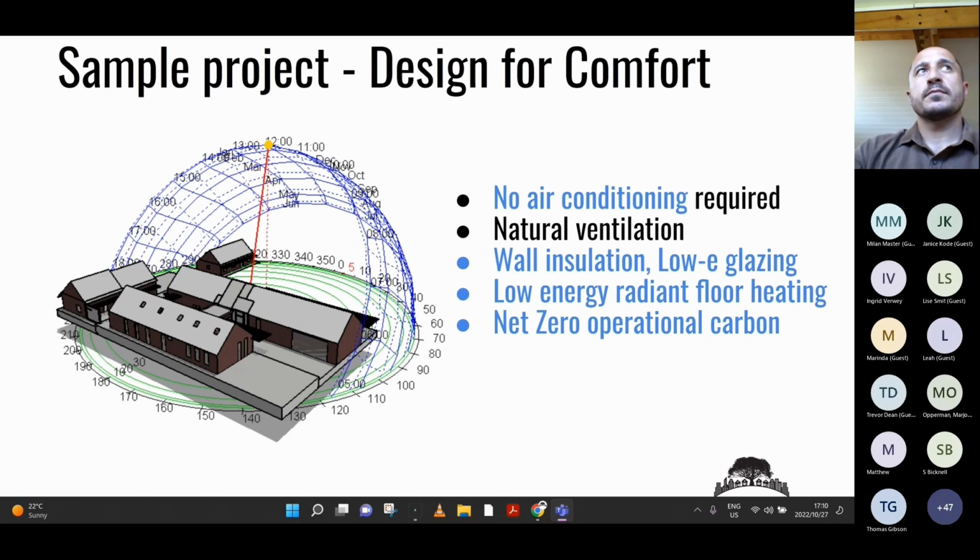And for those that are maybe not aware, ground source heat pumps are basically like your normal air conditioner that you'll see anywhere, in terms of having a compressor to heat or cool the building. But the difference is that instead of rejecting the heat into the air, the heat gets rejected into the ground. So you drill holes into the ground, and then you have your fluid going through there, and heat exchange happens with the ground.